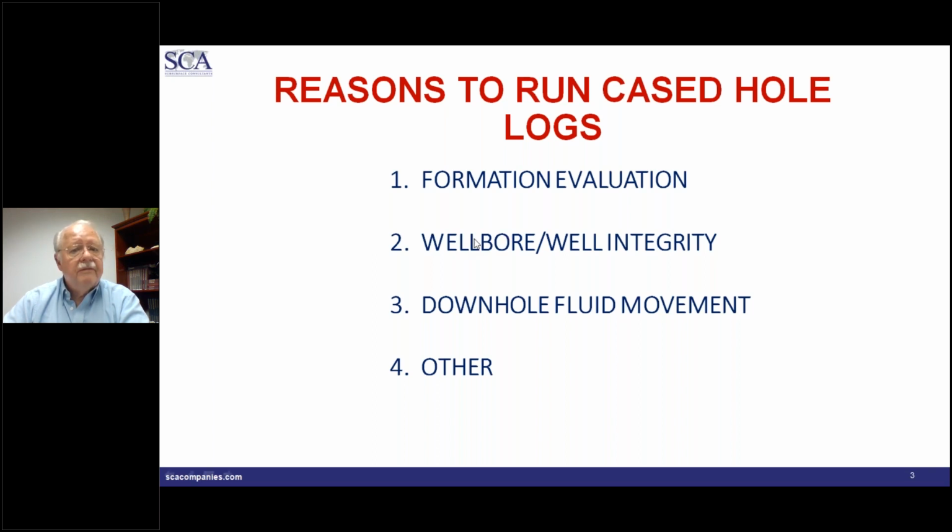The second fairly broad brush category that we're not going to be looking at, but is a part of the cased hole arsenal, is the so-called well-bore well integrity logs. Well-bore means we're looking at the very basic tools to measure the quality of the cement job. You know, that cement is pumped down through the casing, comes back up, and hopefully fills the annulus. Now, we can measure the quality of that cement fill by use of a cement bond log or logs.